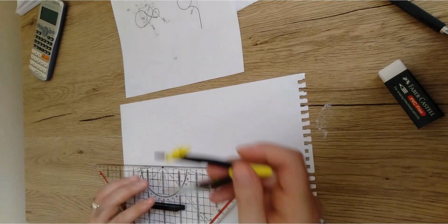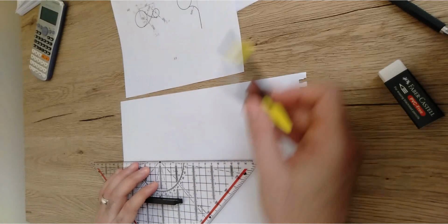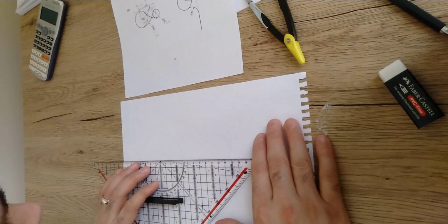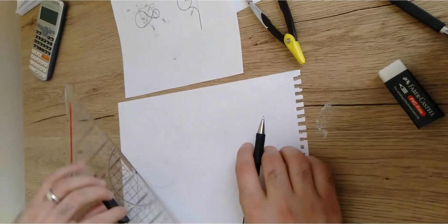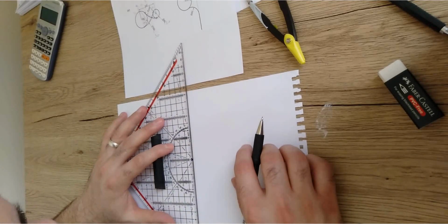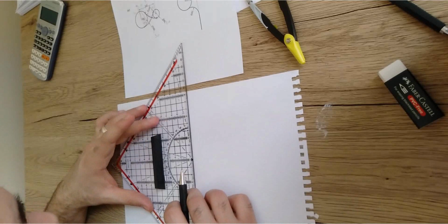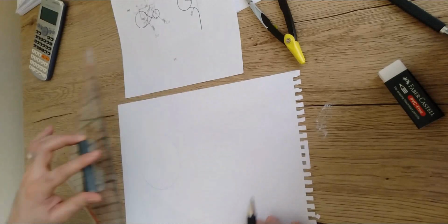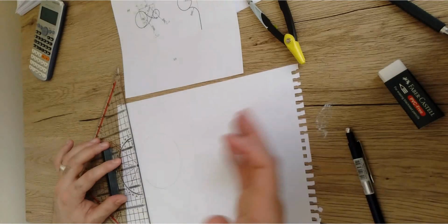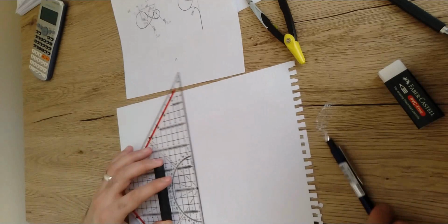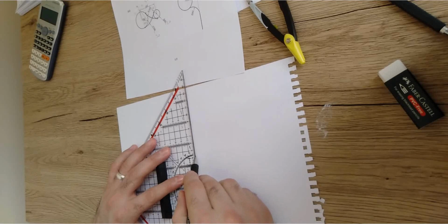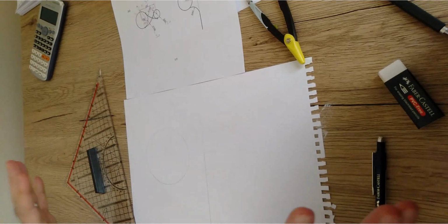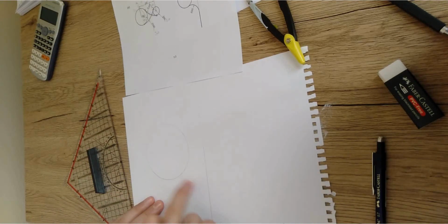Then over this line, I'm gonna measure a distance of 65, and mark a point. Then from this point, I'm just gonna draw a line that is vertical in this way. Make sense? So I got this line, which I'm just gonna make it clear somehow, just to see what I'm doing. Alright, the objective now is just to draw a curve that is tangent to these two objects, this circle in addition to this line.